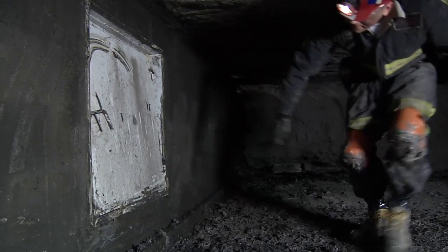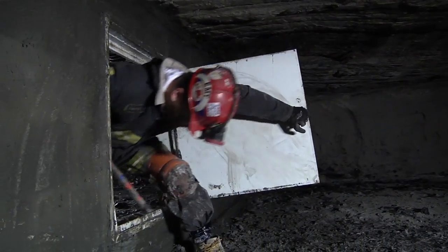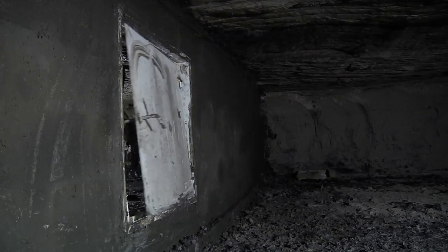Some of the problems with ventilation that I've seen in my time, my career underground, are doors being left open, holes being left in the wall, not patched, the wood blocking on top of the walls not plastered, which is a fire hazard and also lets ventilation short circuit, and canvas not being hung properly or not being hung at all. We've got to make sure it's right.